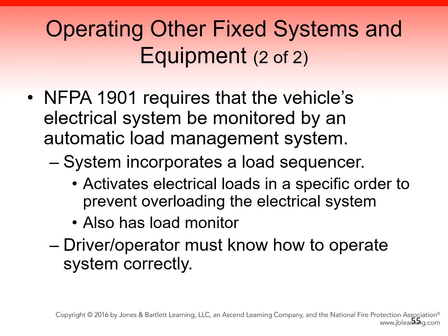The driver-operator must anticipate how the automatic load management system works and learn how to operate it correctly. It is especially important to recognize the difference between load shedding and a possible electrical system failure.